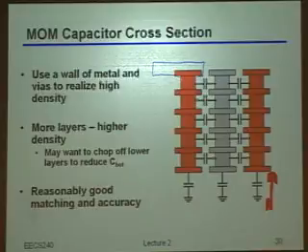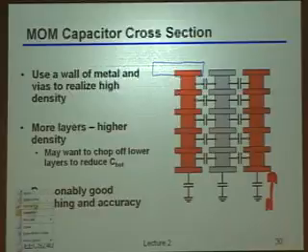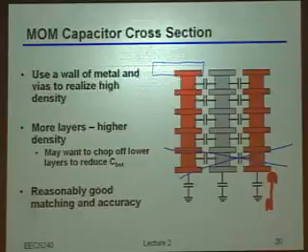So in this context, what would that actually mean? Let's say I took a capacitor that nominally used all of the metal layers. What's the only thing I can do to move it away from the substrate? Yeah, I basically just have to chop off some of the bottom layers, right? So now here's the interesting question. If I chop off this bottom layer, am I guaranteed to get a lower relative fixed parasitic, for the same total value of capacitance that I really wanted, or not? No, right? Why not? What's the trade-off?